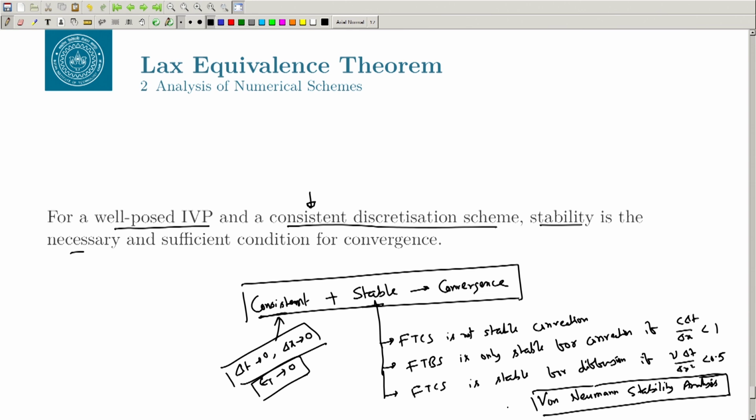So, you might be disappointed that the Navier-Stokes equation that we are trying to solve is a nonlinear problem, right. So, how do we use whatever results we get from the stability analysis? Despite the fact that we are using it for the linear scheme, the observation that we get is actually quite useful for a nonlinear problem also. Unfortunately, we do not have an analysis approach that can work on a nonlinear problem, because it quickly becomes very complicated and it is very difficult to perform that analysis.